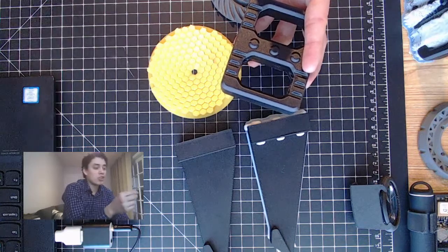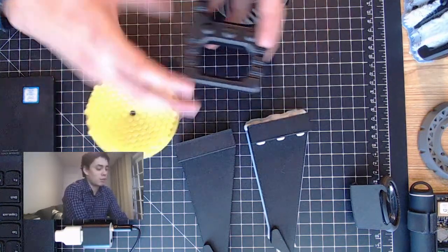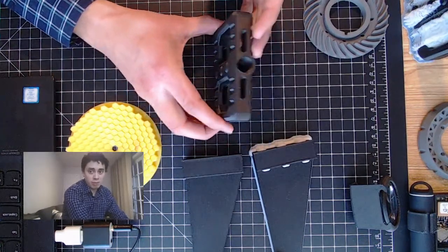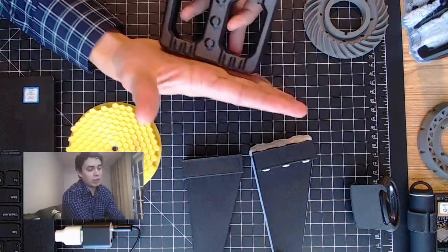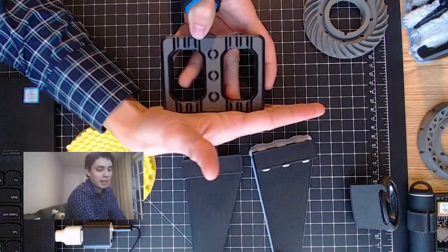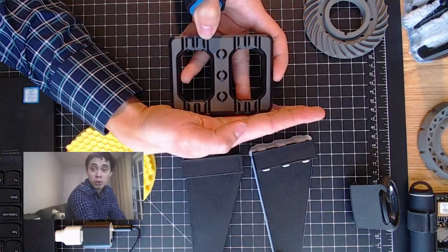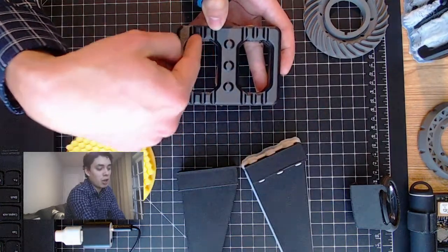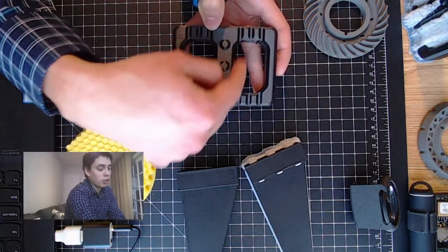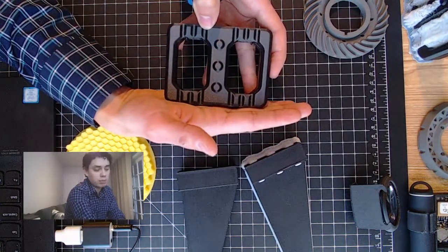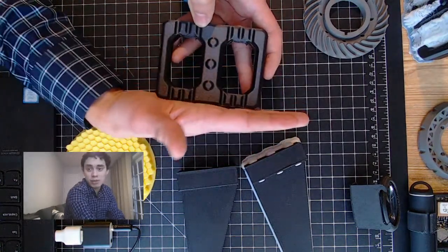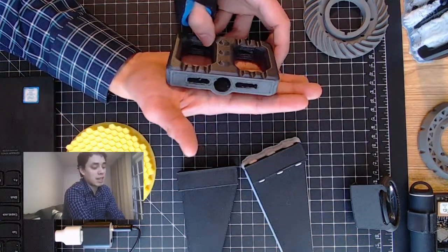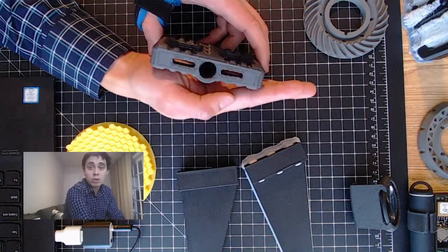Now, second consideration: how does this affect my material usage? Meaning, how much support material will I require by printing this particular part this way versus this way, right? If this is my build plate and I print it as I was showing you before on Cloud Print, oriented like so against the build plate, then all of these insides will probably be covered up in supports, because this bridge at the top is unsupported at the moment. However, if I was to print it flat on its side, I will be using way less support material,